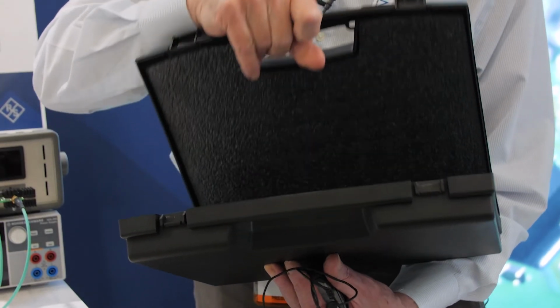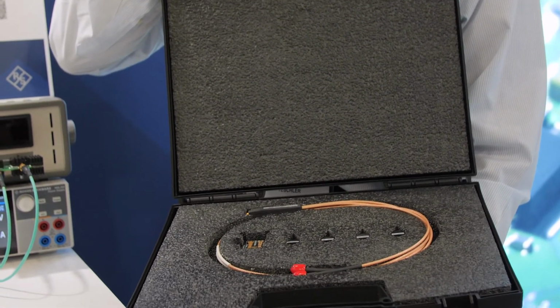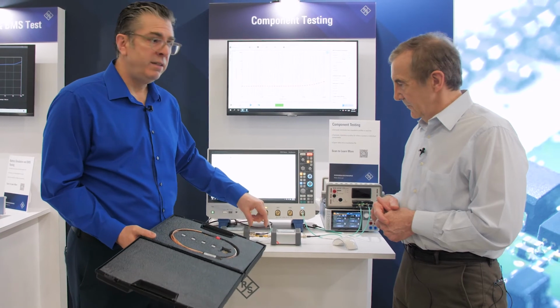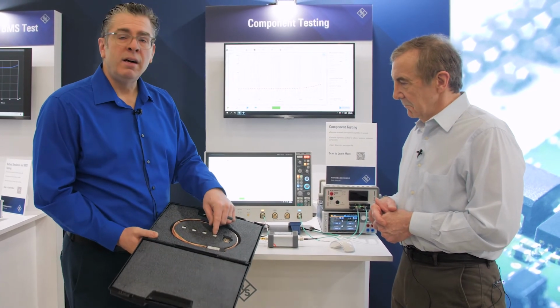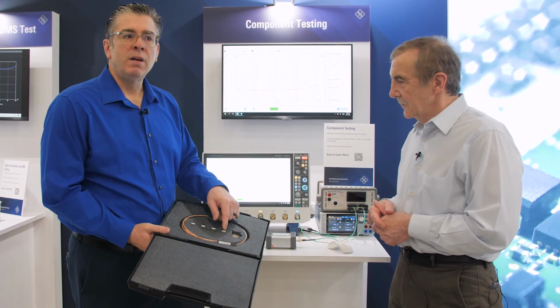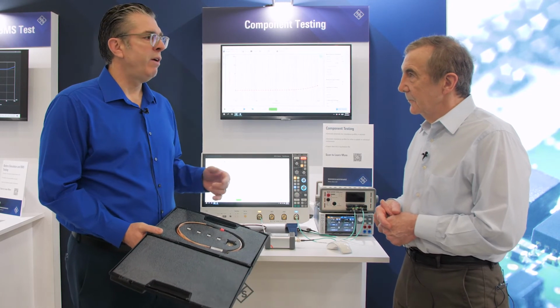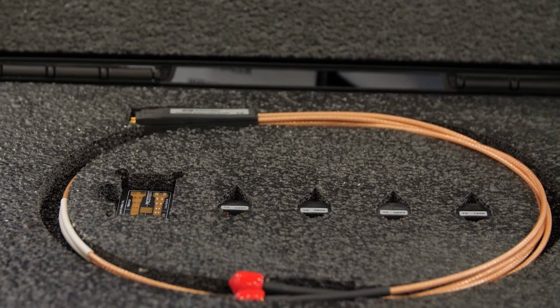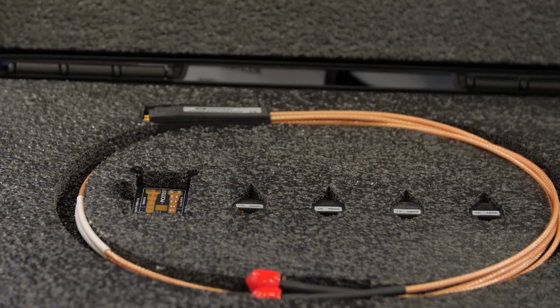PicoTest, for doing actual component testing, enables you to use a probe. You would use this probe to snap in, and it has probe heads with different spacing, like a 402 or an 805. So if I'm looking at a server and I want to do multiple power rails, it gives me the impedance value that I'm looking for.